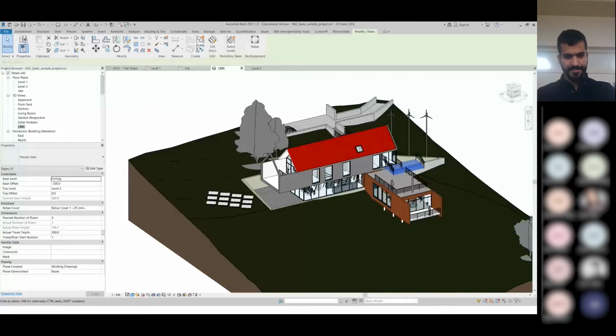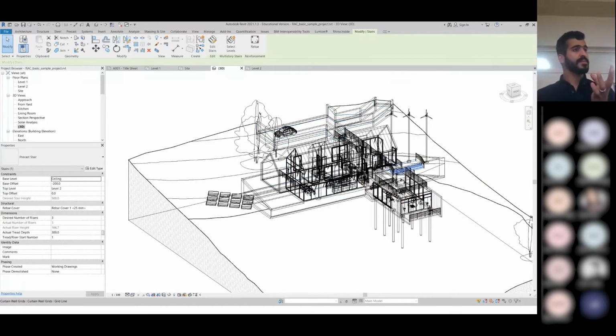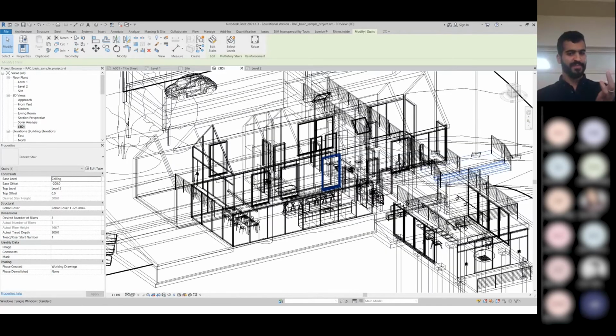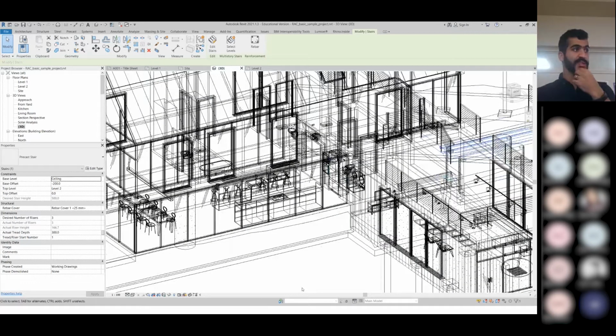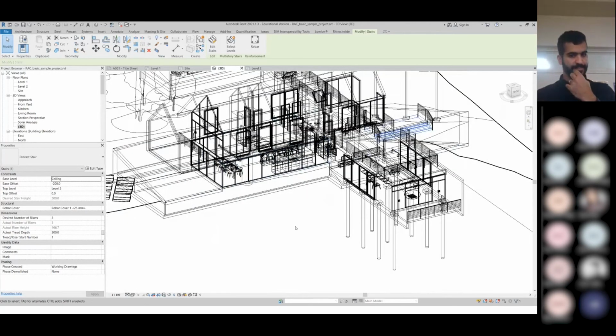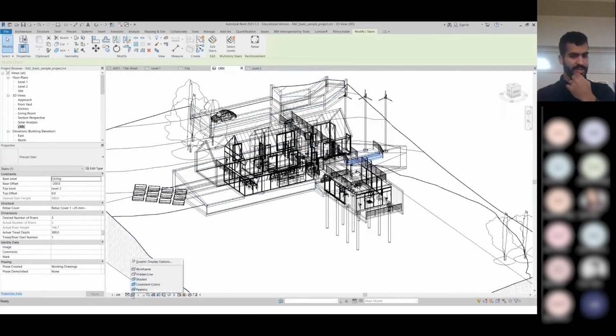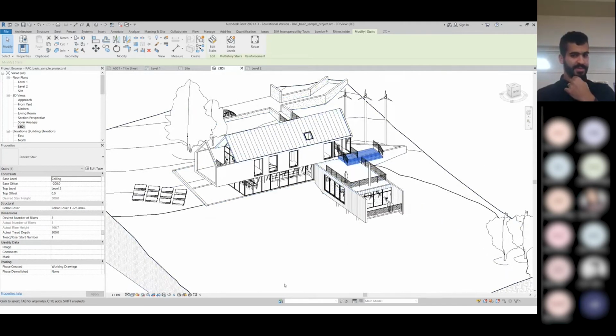At the bottom here, you can control different things. You can control the drawing itself and what it presents to you. If you go on wireframe, it makes everything into a frame. You can see how this is looking interesting in terms of a representation in a drawing, for exporting line drawings and overlaying images together. Here, you can also try doing hidden line. It gives you a very clean line drawing.